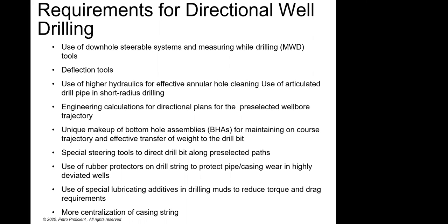And further down, once you run the casing, centralization of casing is very important. In vertical wells, it's important, of course, but in deviated wells, it becomes more important because you want your casing to be in the center. You don't want it on the lower side of the well, because the cement needs to be uniformly distributed around the casing in order to ensure proper zonal isolation.